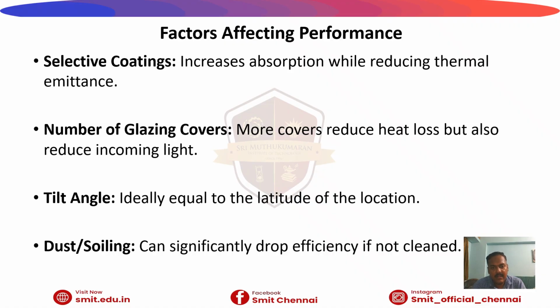Tilt angle should ideally equal the latitude of the location. If the tilt angle is changed, we get a loss in energy. Dust and soiling can significantly drop efficiency. If the solar panel or module is dirty, the efficiency will be very low.